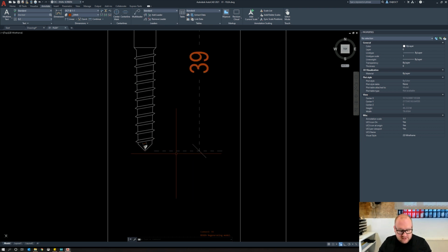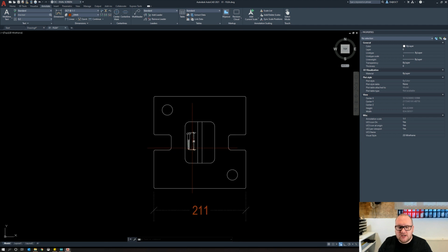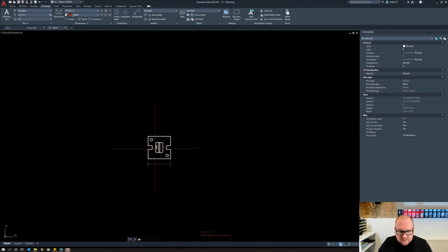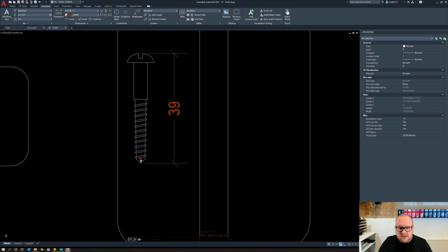And you can see, I think the biggest difference there was the line type of the dimension changed. If I zoom out, see if I can get it to do that again. In fact, if we look at this dimension down the bottom here, if I hit RE, no, it didn't affect anything. If I zoom in and then hit RE, you see it's regenerated the line, so it's in the proper dashing style. I suppose that's the biggest difference.